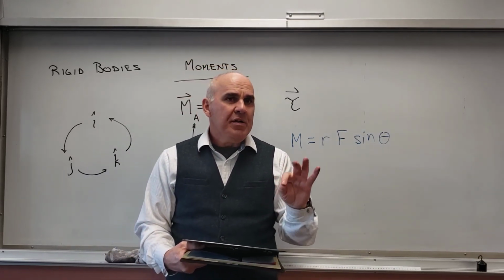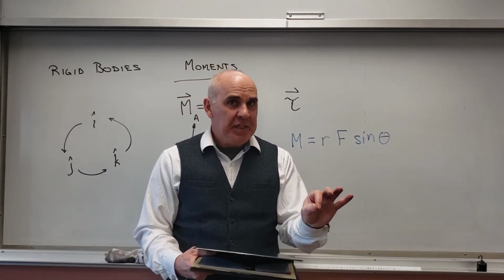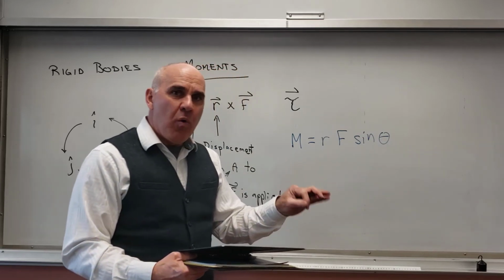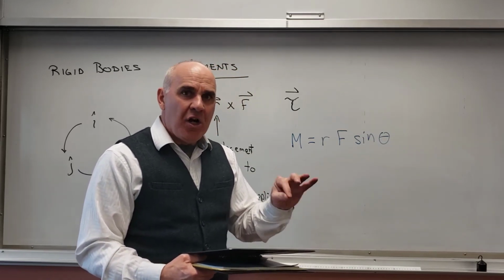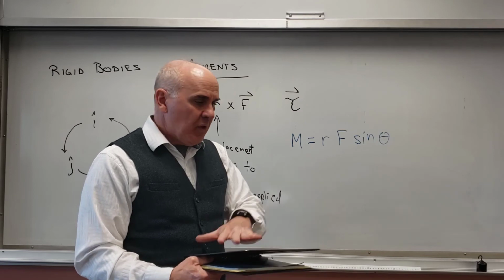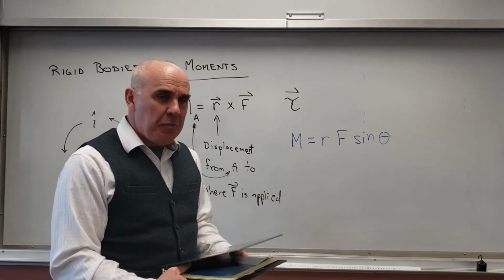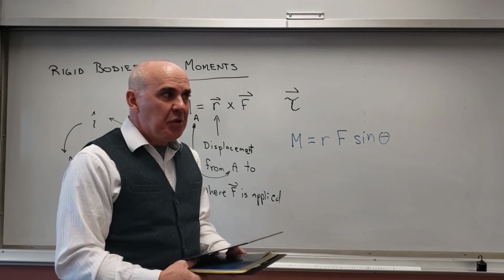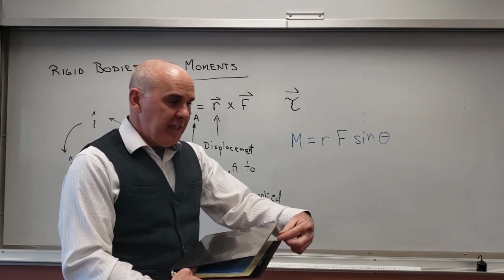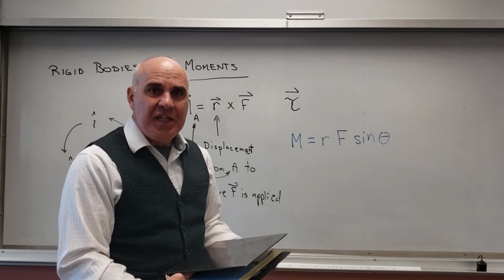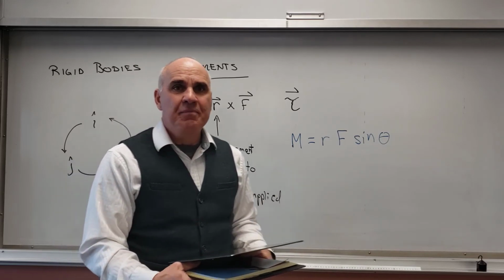Okay, so where the force is applied makes a big difference. And then at what angle the force is applied also makes a big difference. All right, so that's a little bit of a lesson then on moments. Just go and open the door and push at different locations and then push at the edge of the door towards the hinges, and you'll see it doesn't open the way you think it would.